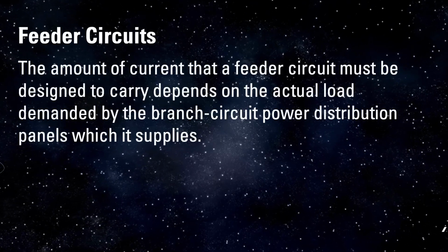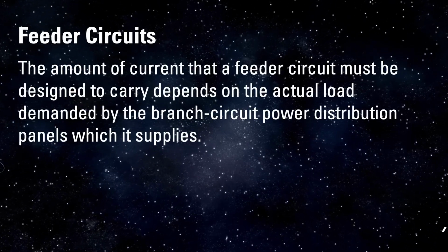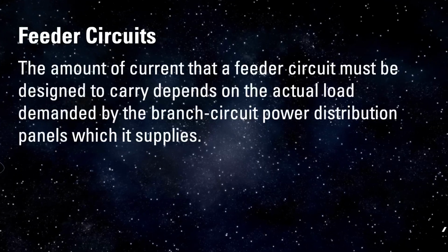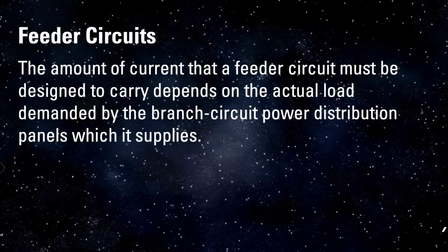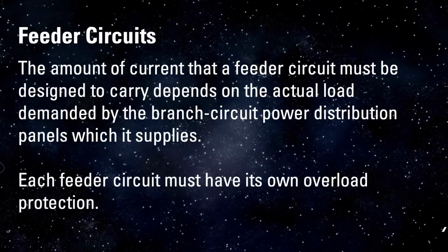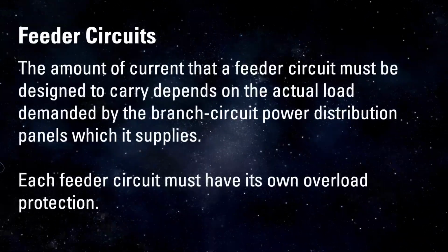The amount of current that a feeder circuit must be designed to carry depends on the actual load demanded by the branch circuit power distribution panels which it supplies. Each feeder circuit must have its own overload protection.